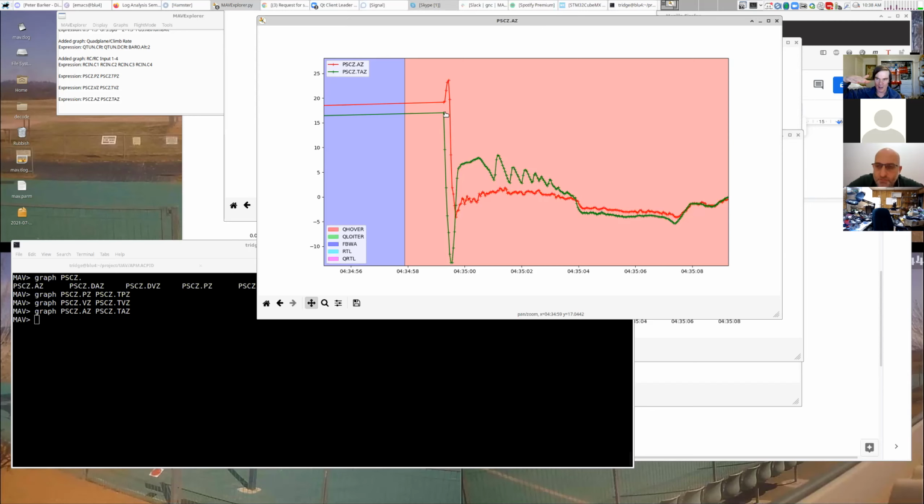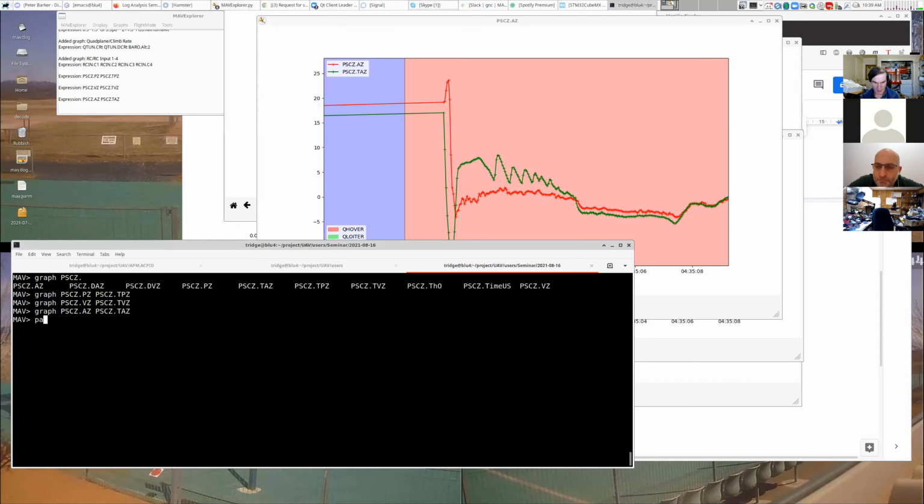And then the elevons bring you up, and then once you've started to slow down and come up to a certain angle, it hands over to the VTOL controller, which brings you then to the last part. So that's what we're seeing, this gap here, where it's not starting the vertical controllers until it gets to this point. And so we can see here that the point it starts the vertical controller, the vertical acceleration is really quite high, right?